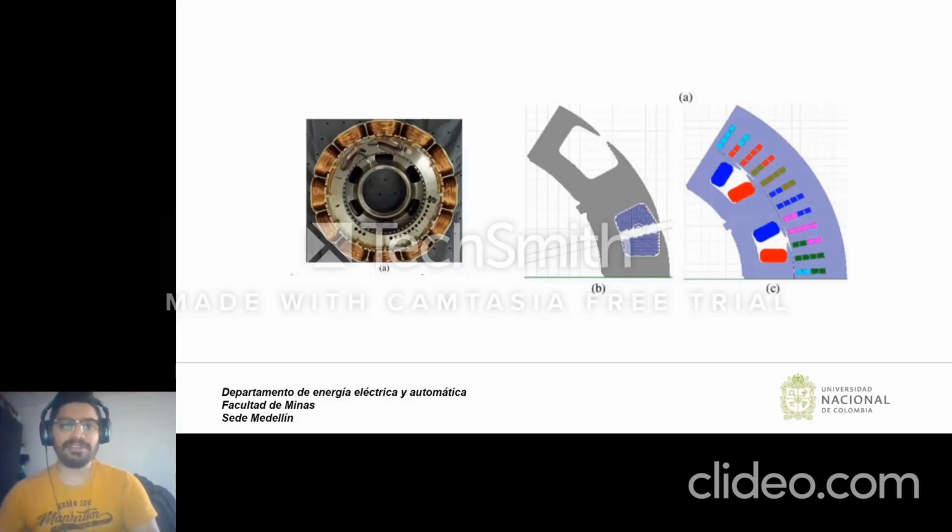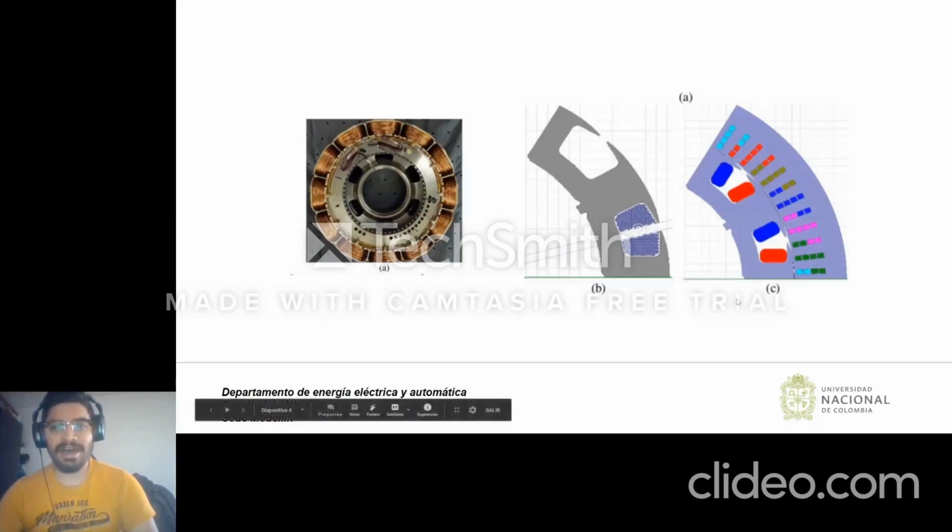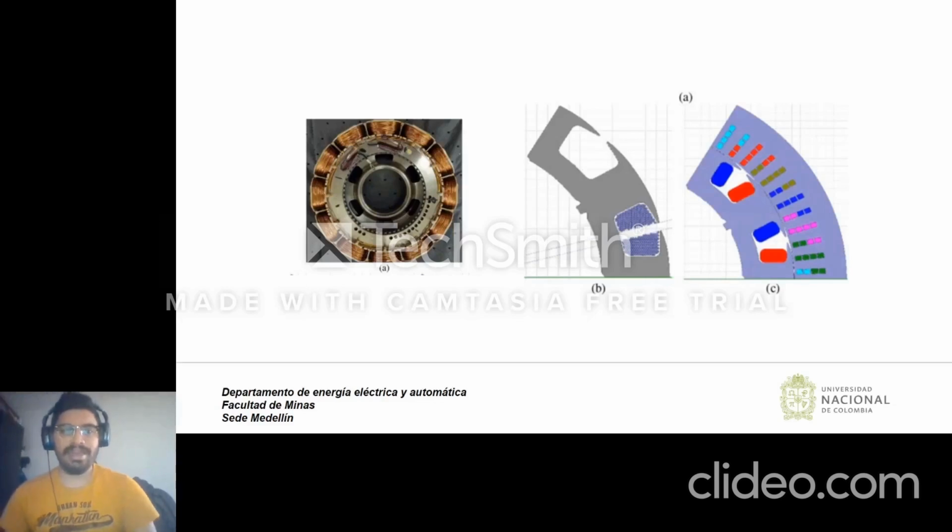And now this figure shows the final geometry of the optimized design. Now it's possible to see the machine and the optimal design of the geometry. The design is optimized for maximum torque and specific power, efficiency, and torque ripple requirements. Torque ripple is optimized by adjusting three design parameters.